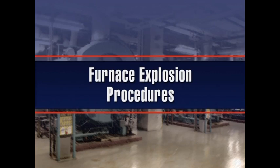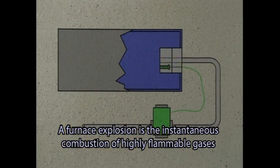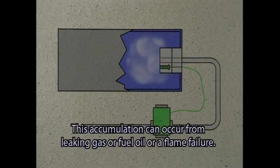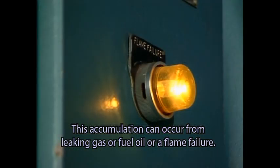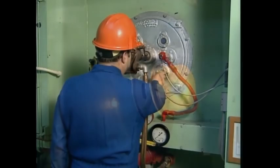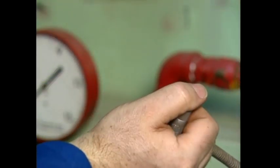Furnace explosion procedures. A furnace explosion is the instantaneous combustion of highly flammable gases or vapors accumulated in the furnace. This accumulation can occur from leaking gas or fuel oil or a flame failure. Any signs of leaking fuels must be addressed immediately. The flame scanner should be checked for proper function.